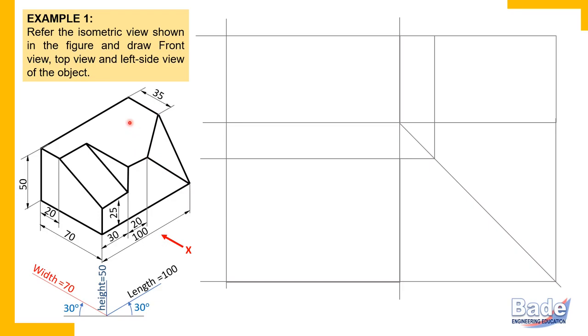So first be sure that you have understood what a principal edge is. Its significance you will understand in a little while. But try to understand what a principal edge is, and remember it. Okay. Now, principal surfaces. The surfaces which are parallel to the reference planes, that is, a surface which is parallel to HP, a surface which is parallel to VP, a surface which is parallel to PP, these are principal surfaces. Now this is a principal surface. How will you come to know that this surface is parallel to HP?